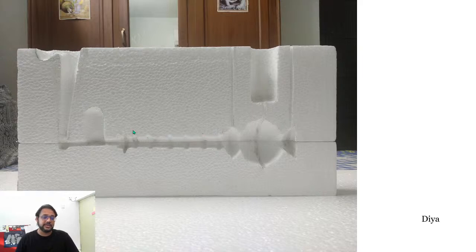So all of these locations you would need some vents. And the other mistake that I think Dia has made is this riser. Generally, risers don't have a very small channel leading up to them. The idea of a riser is that it is a place for the material to overflow. So it would need a fairly bigger channel than this small one, which is the same size as, let's say, the air vent.